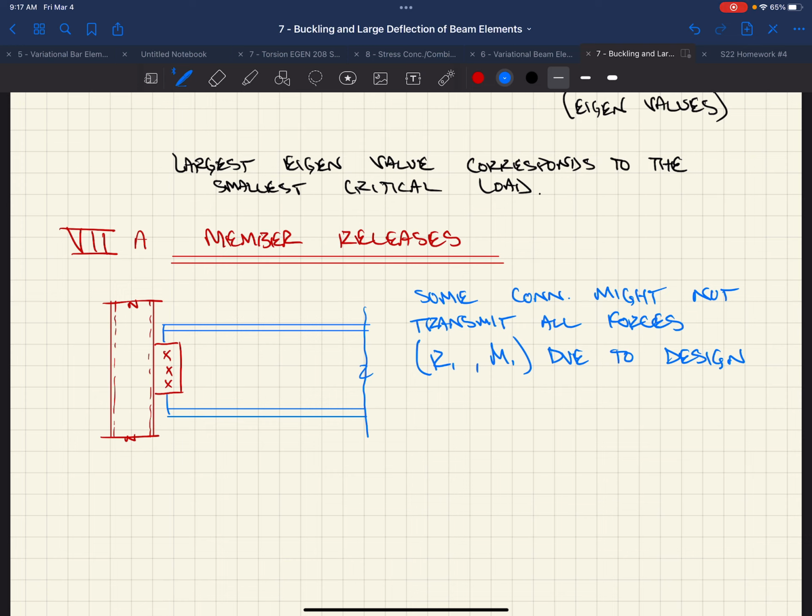You get into trouble then, if you have a lightly loaded section that's a little oversized, and you call it the same shear tab as you do with a more heavily loaded section. I mean, you could if you were really nitpicky, but you gotta kind of step back sometimes and squint. For the most part, as long as the tab meets the design requirements in the manual.